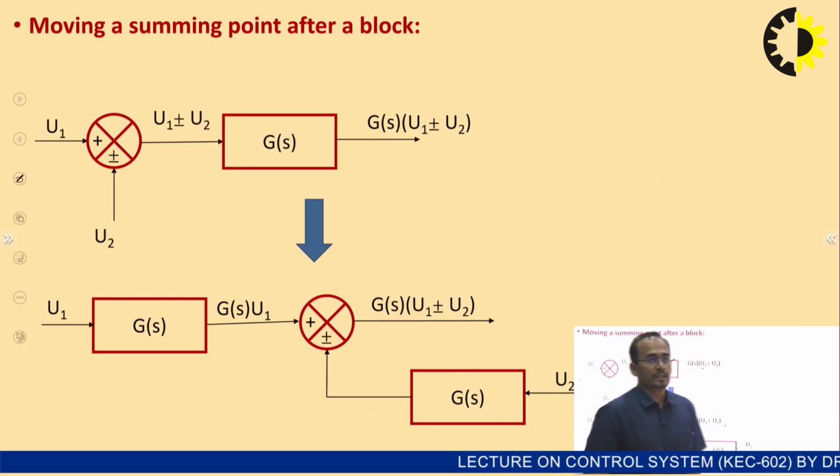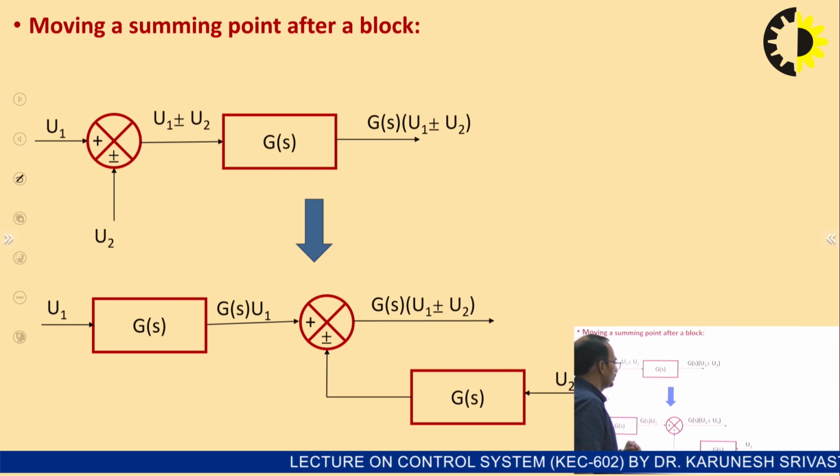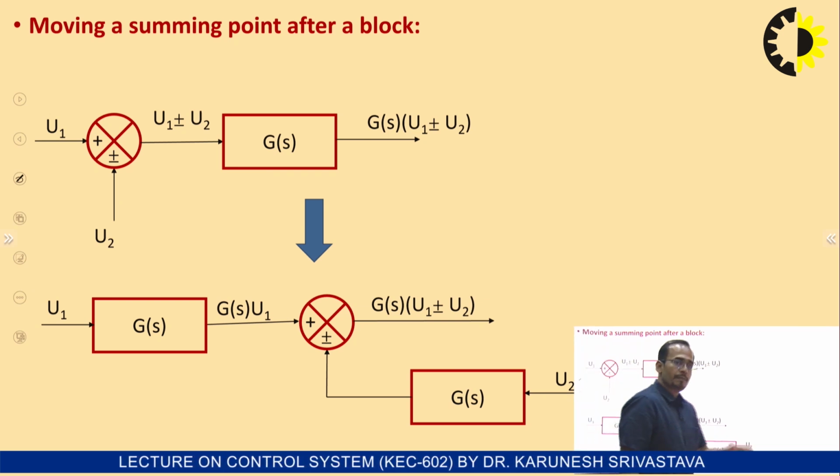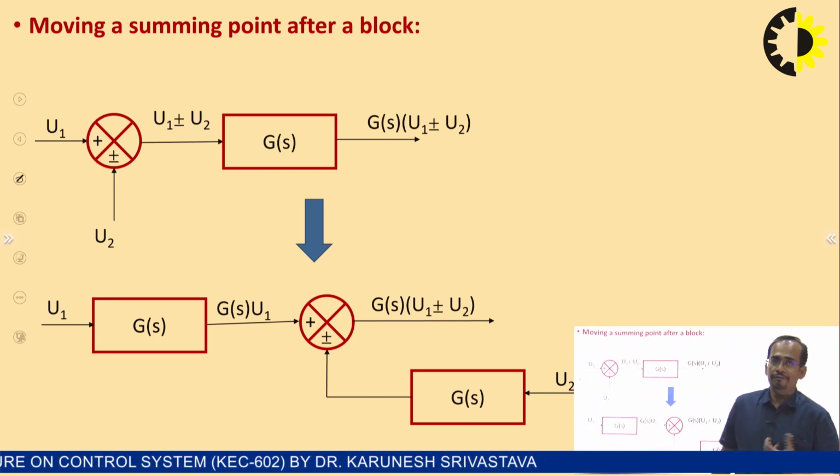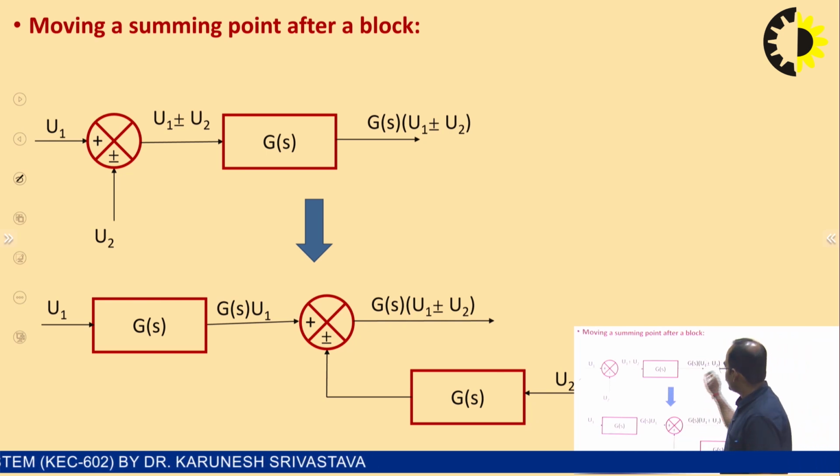Now the next rule is moving a summing point after a block. If I shift the summing point to after a block, the output should not change.